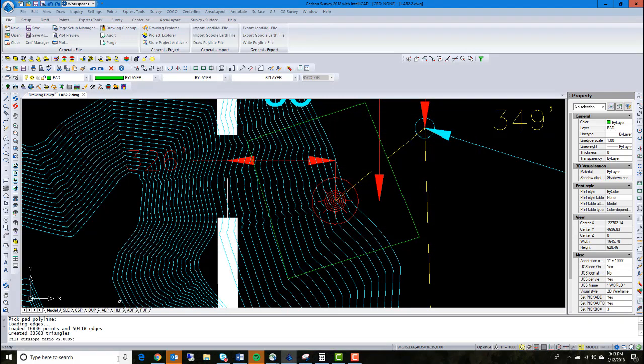So now it's going to ask me what slope do I want to make my pad. So you imagine you have a pad and you might be cutting into a hill or actually building up some area from that scenario, and I'm going to need a ratio. A 2-to-1 ratio is for every 1 foot out you go 2 foot down. It's just very common, so we'll just keep that. And on the cut side we'll have the same 2-to-1 ratio. Now it's asking me what do you want to make the pad elevation.